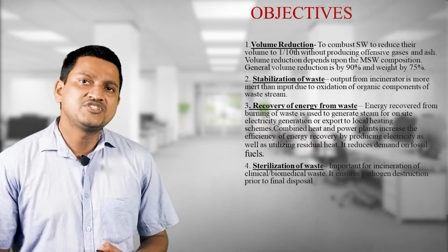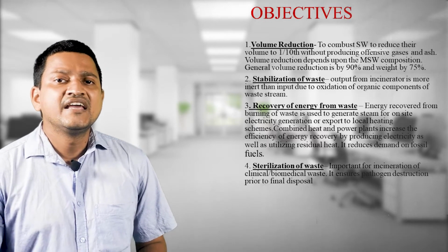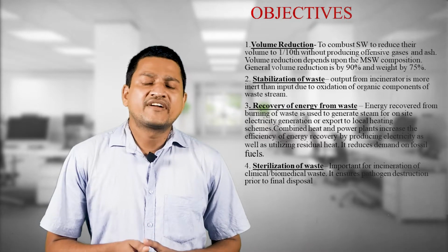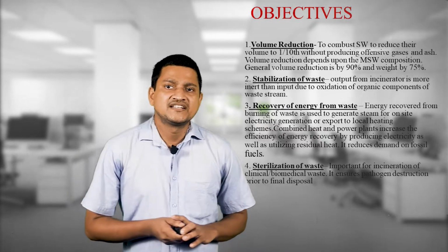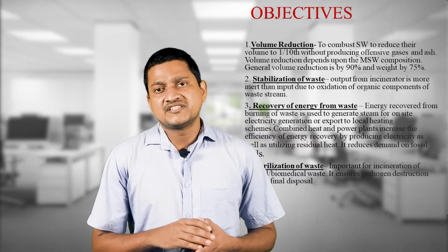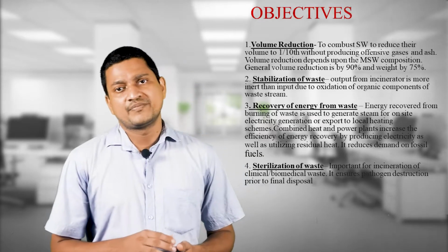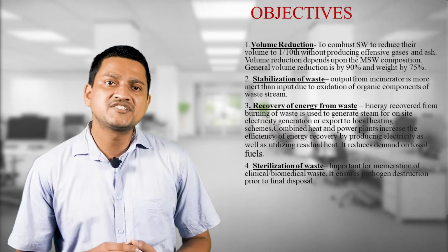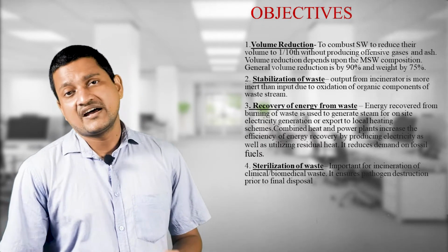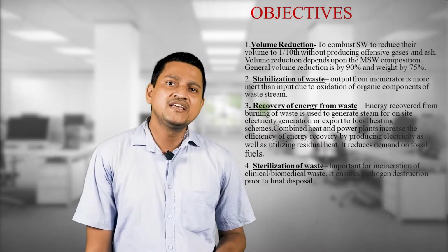And the fourth objective of this incineration is stabilization of waste, important for incineration of clinical and biomedical waste, that is its stabilization property. The temperature stabilizes this type of material to a stable form. That means it ensures pathogen destruction prior to final disposal. That's another advantage or objective of the incineration.